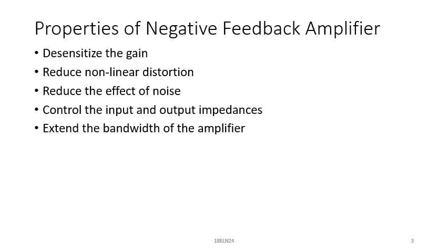The third property is that it reduces the effect of noise. You know that noise is an unwanted signal. In amplifiers, this noise will be added due to temperature variation or due to your circuit components. And if I use feedback, the noise will be reduced.